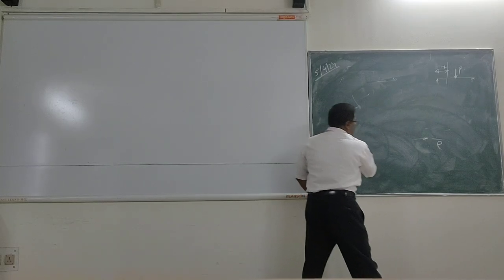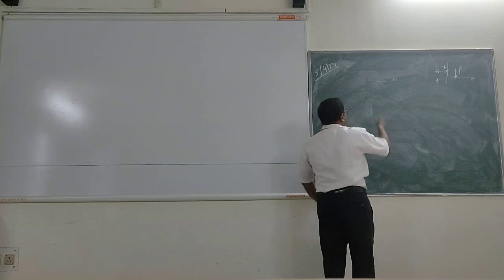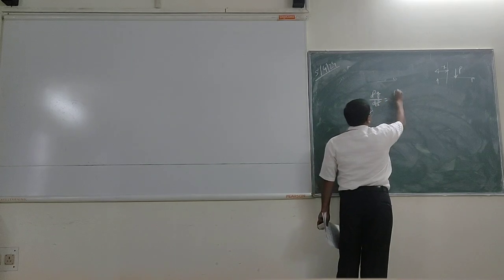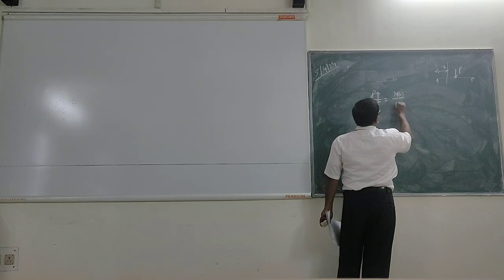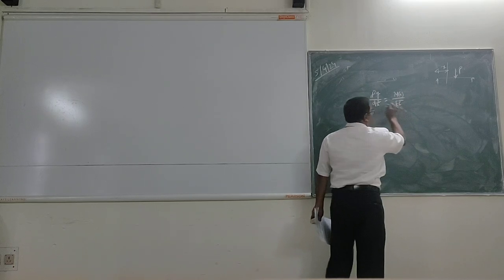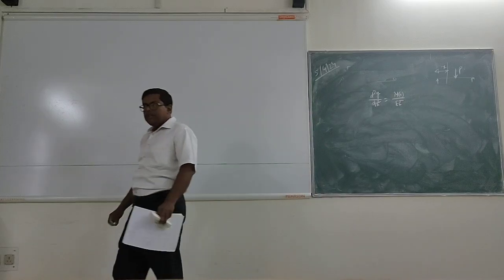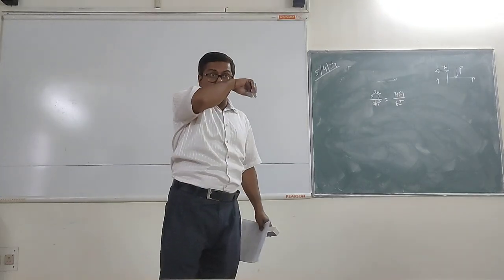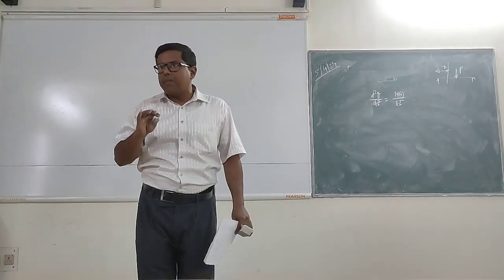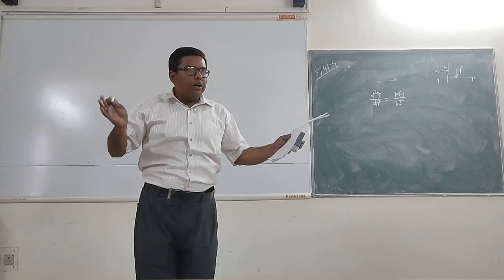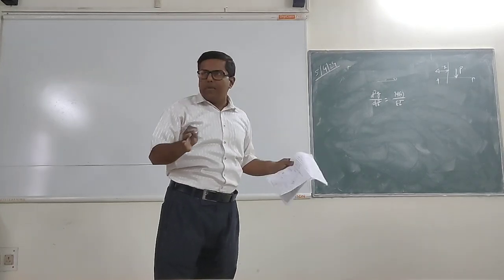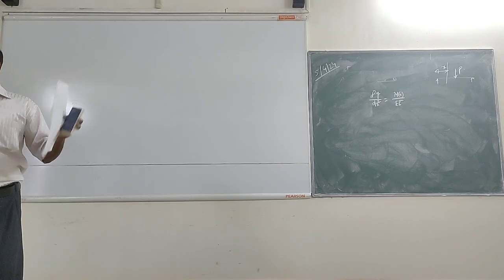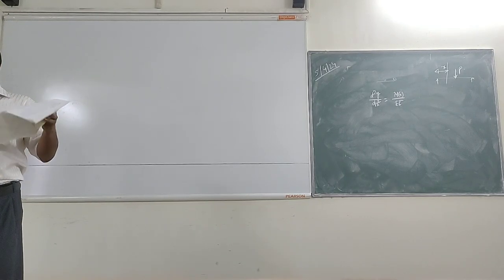Now you can see why it is being called the double integration method. The formulation you have now is d2y/dx2 equal to M(x) by EI. Now what is this EI term? EI is a constant term, flexural rigidity. It is a constant term for a particular section of the beam. If I take a rectangular beam, I will be constant. For the particular material, E will be constant. So EI is constant. What is varying? The varying thing is your moment. Based on the load, the moments will change, right?